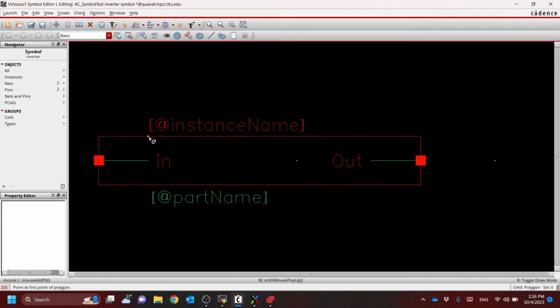I'm going to start off in this top portion right here. I'm going to click. That's going to tell it to start drawing. I'm going to drag it down, and you can see that it's starting to draw a line. Now, if I click here, then it will set this point. So now if I move around, this line right here is set. Now I can continue this way to make an inverter symbol. If I try and keep everything centered, I can keep it aligned with this pin here. I can move it maybe over here, click one more time, and then move back to the beginning, click one last time. Once we make it back to the beginning, then it will actually stop drawing and say that we have this polygon finished.